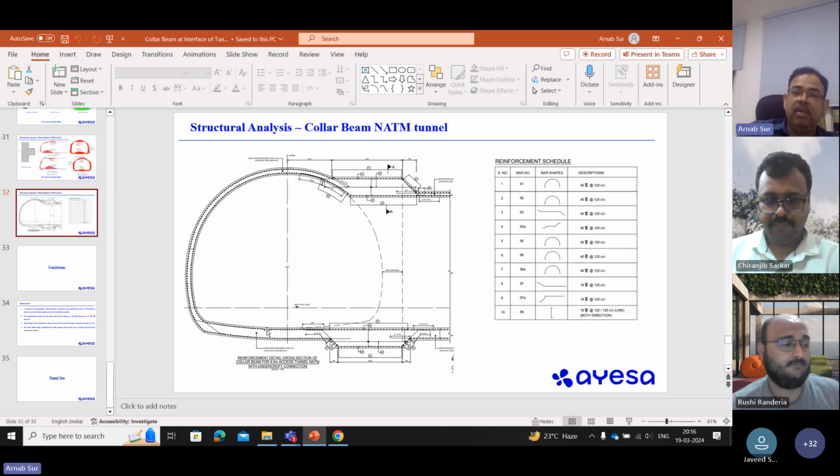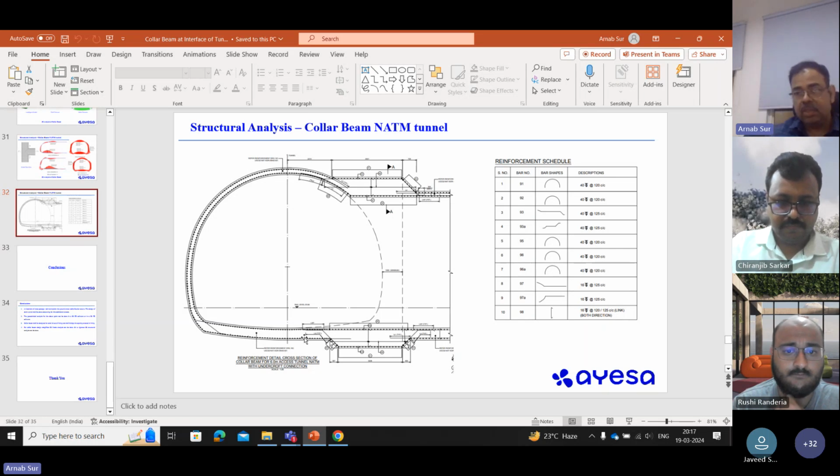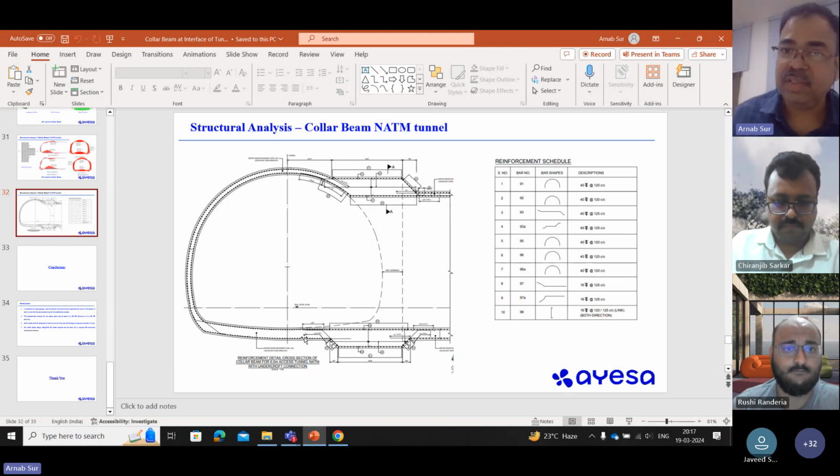Look, if we speak about CJ, it can be between the invert lining and the overt part. CJ can be along the length of the tunnel. And at the cross passage area, since these collar beams are cast later, we provide some CJ here also. So CJs are based on construction requirement mostly. Generally, we civil engineers want to avoid construction joints and want a minimum number of them, because construction joints create problems, they create water seepage. But there is no reduction in strength because of a construction joint, because all the construction joints are treated for 100% strength.